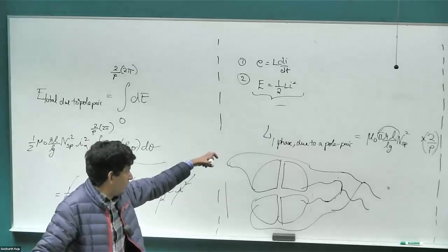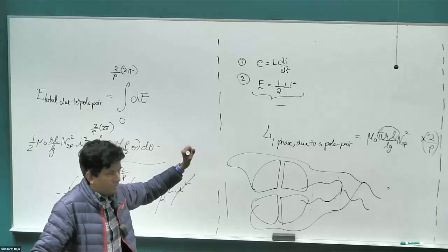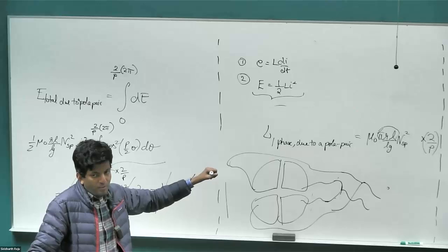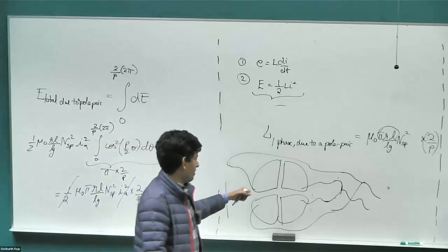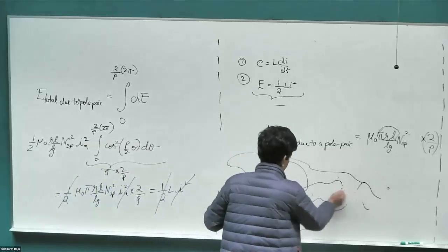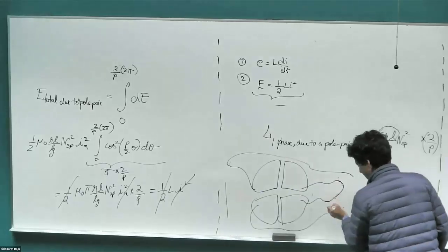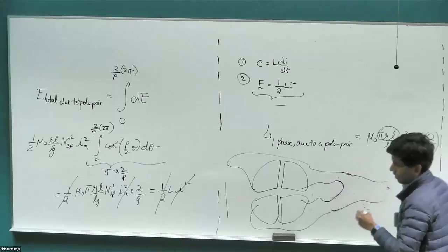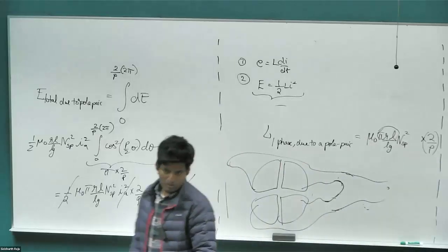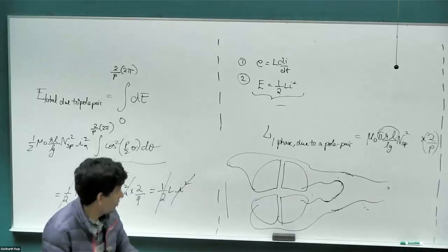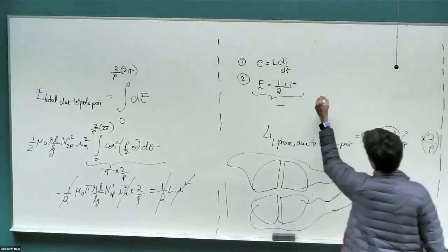So that is the inductance for a single phase for just one pole pair. And then similarly, I will have an inductance for another pole pair. If both of these coils were connected up in series, like the case here, so one coil pair is connected in series with the other and I take the coils out, what will be the net inductance? 2L. Perfect, just 2 times. So if I do it in series